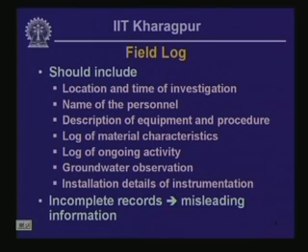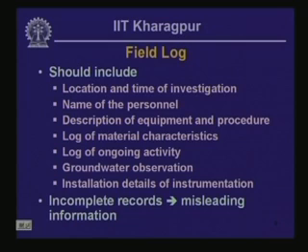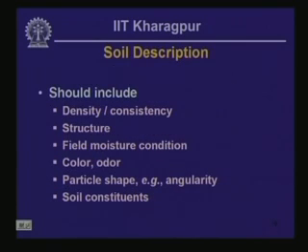Then installation details of any instrumentation like a standpipe piezometer. We are going to look at the details of these things later on. So instrumentation details should also be mentioned on the field log, and as I mentioned earlier, an incomplete record is really a misleading set of information.